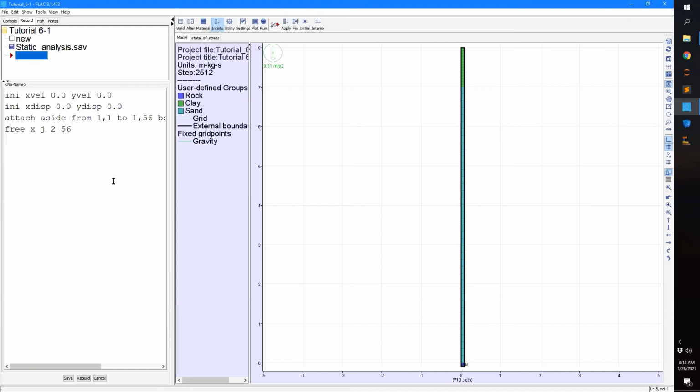I feel like that does a pretty good job for the frequency range that we're typically interested in for seismic applications. What I typically target is on average about 0.5% damping for a model like UBCHYST that does a pretty good job of capturing damping, and then on average 1% damping for the rock.